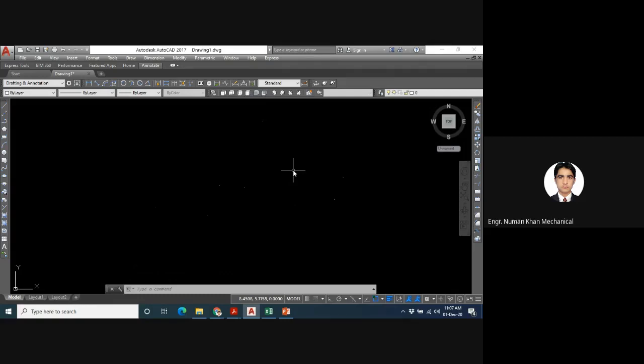It's just a point. But in CAD, we have some advantage that we can increase the size of the point relatively to the screen or absolutely, but that does not mean that we are changing the point concept. We are just changing its shape or type for visibility purposes, to be clearly visible in the drawing. Because if you draw some points in the drawing and you print it, that will be just a dot and that will be very difficult to interpret. So we change its shape or size to see it clearly, to interpret it very easily. So we do it by changing its shape and type.